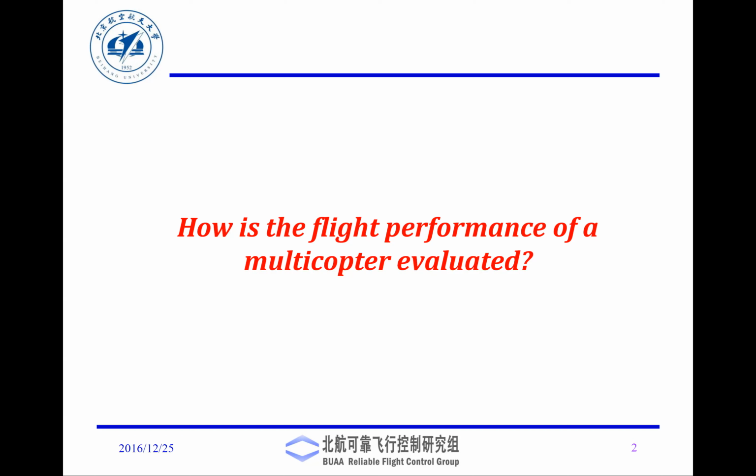Now, one thing I want you to observe is that these motors just have 3 wires coming in. Even though we are supplying positive and negative, what the ESC does is take this DC supply and convert it into a 3-phase AC supply. And these phases run at certain phase angles that will cause this motor to rotate.